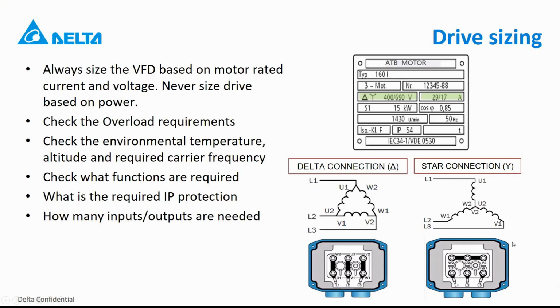You also need to check how many inputs and outputs the application needs. See if the drive actually has that, or if you need to use some IO extension, or if it's maybe more convenient to use a different drive or just use an extension module.